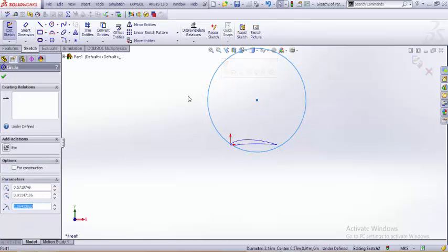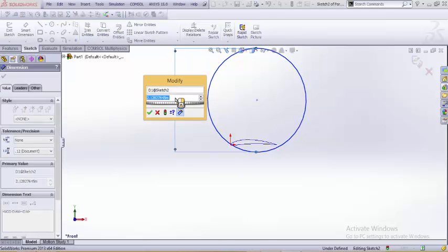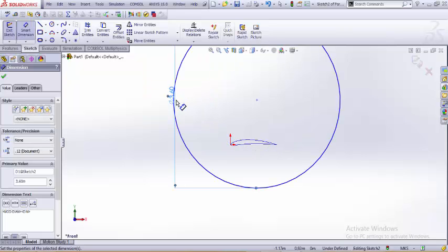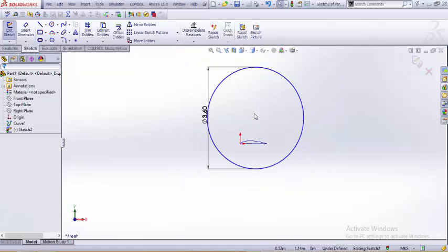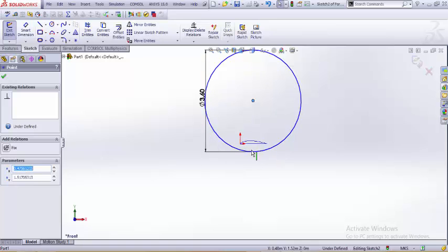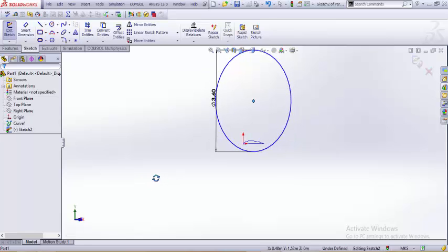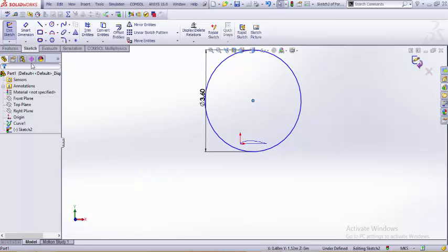Let's set this one as 3.6 meters. Move this to a position that this curve is at an edge, since we want this to be on the sides and it would be acting as a blade of the wind turbine. So that's it, good enough for us.